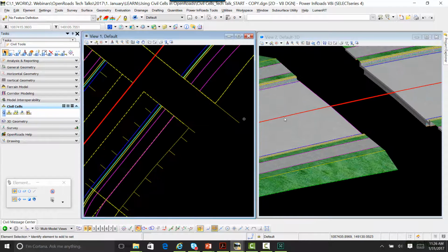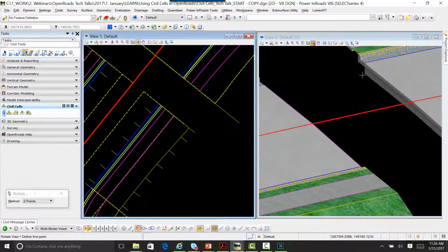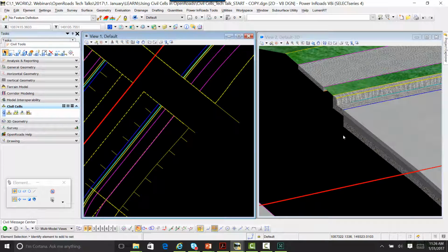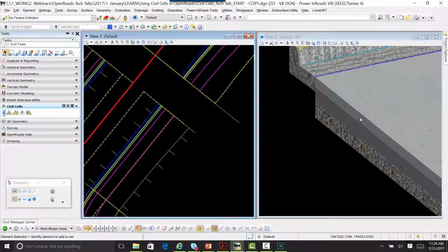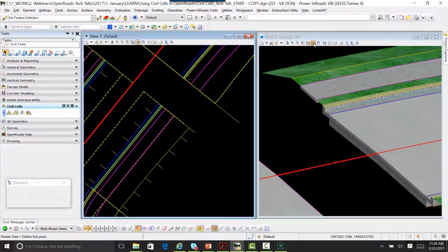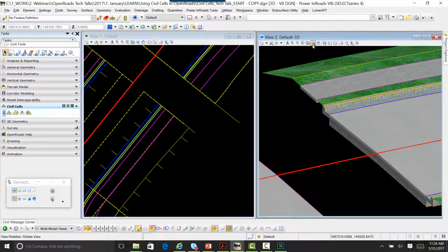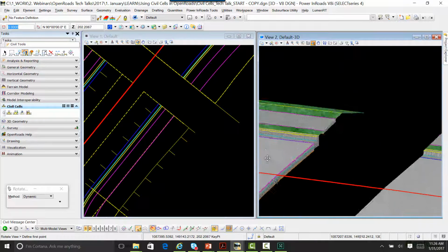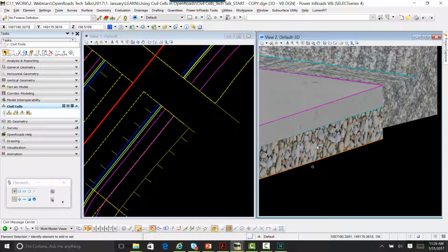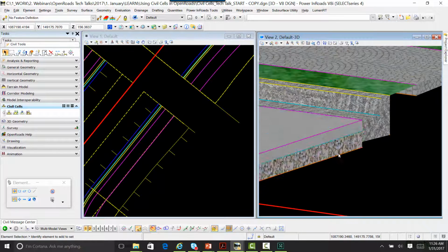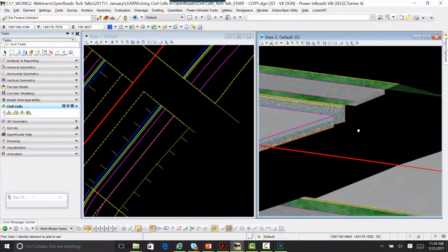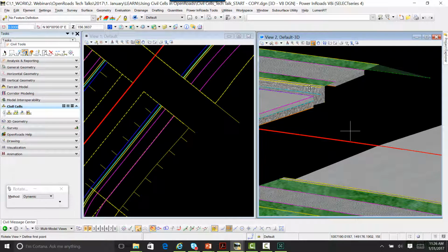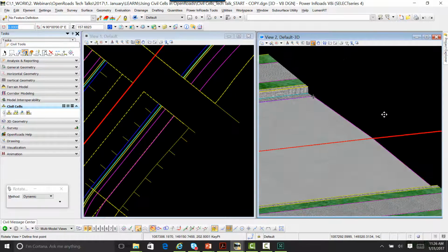Notice if we zoom in here, if errors should occur, let's take a note. Our adjacent corridor, we've got 3 pavement layers here. And let's take a look at the pavement buildup based off of what was in our civil cell. And notice, just very basically, simply you have 2 layers within the intersection and 3 layers within the roadway corridor.